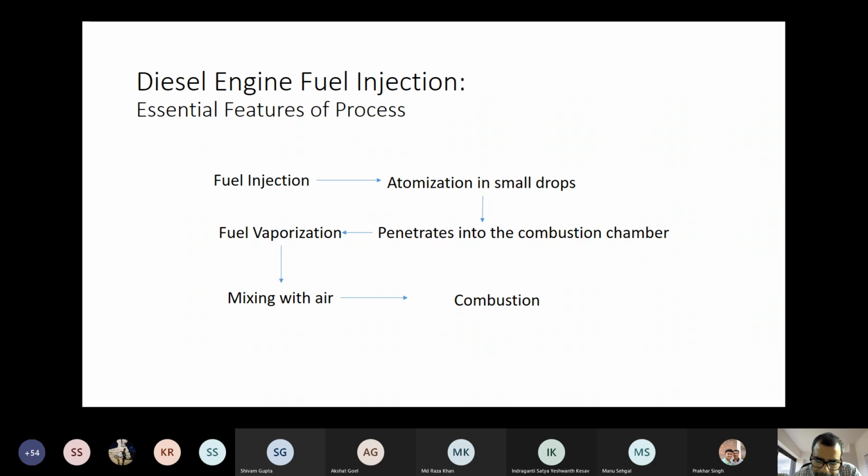We have studied that the air-fuel ratio in the diesel engine has a wide range of variation compared to the SI engine. The SI engine most of the time runs on a stoichiometric air-fuel mixture. The diesel engine rarely runs on a stoichiometric mixture; it always runs towards a lean air-fuel mixture.